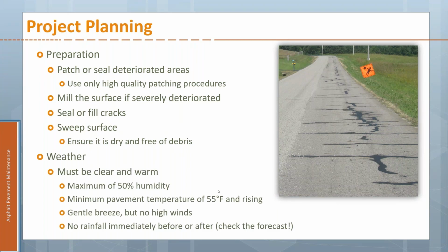The chip seal process is best done when it's clear weather, warm, hot. Summertime is a great time, but the minimum pavement temperature should be 55 and rising. And so I would target that as a nighttime temperature, be your 55.